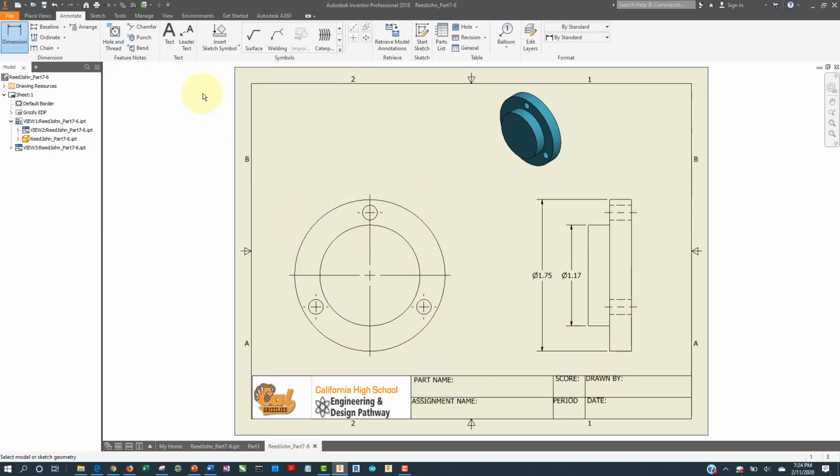While we're at it, we might as well do the depth. So I'm going to use the baseline tool to click here, left click, right click, continue, and for now I'll put this up here, create, and move that out of the way. And I think we might have pretty much everything with the right view completed at this point.